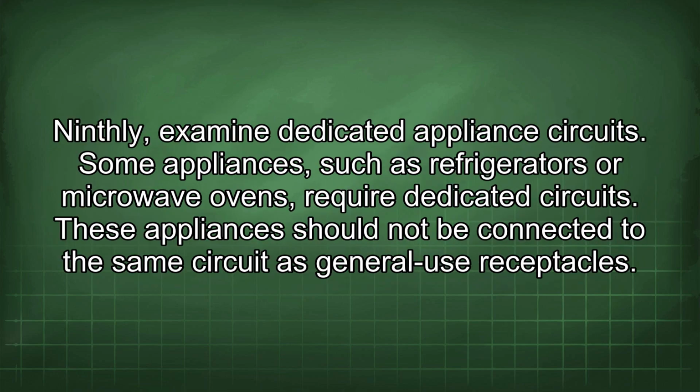Ninthly, examine dedicated appliance circuits. Some appliances, such as refrigerators or microwave ovens, require dedicated circuits. These appliances should not be connected to the same circuit as general use receptacles.